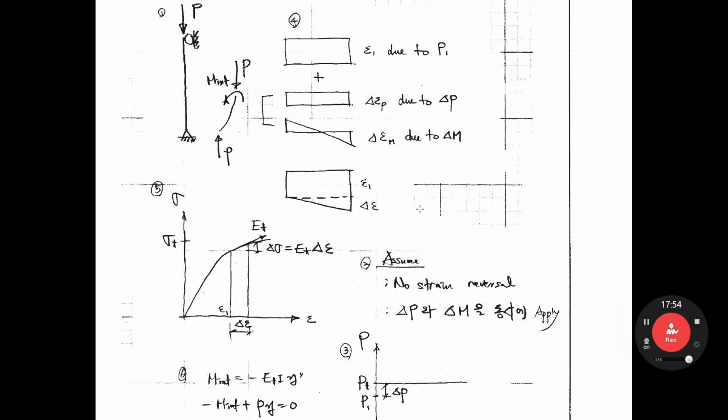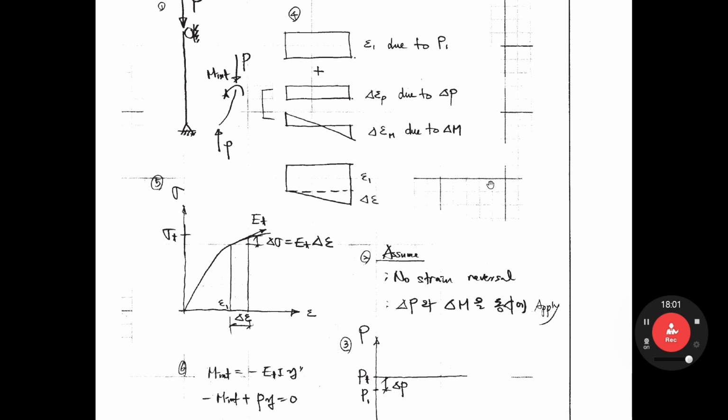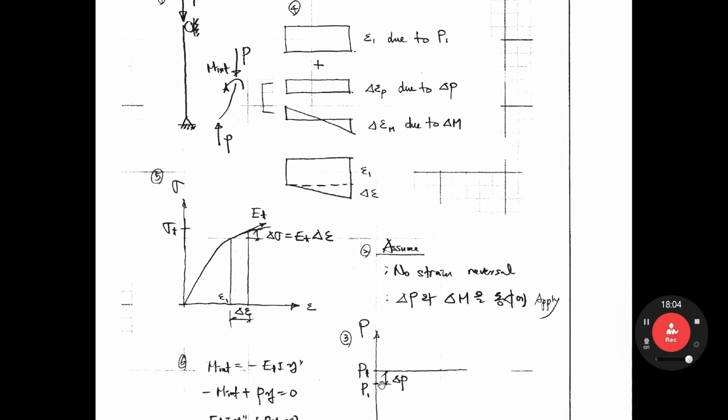So when the buckling occurs, the strain status is like this. As you see, from epsilon 1, the strain always increases, at least greater than or equal to 0. So the strain increases on the right hand side, so the stress can be calculated following this slope called E t, the tangent modulus. This is the tangent line, right? So the tangent modulus.